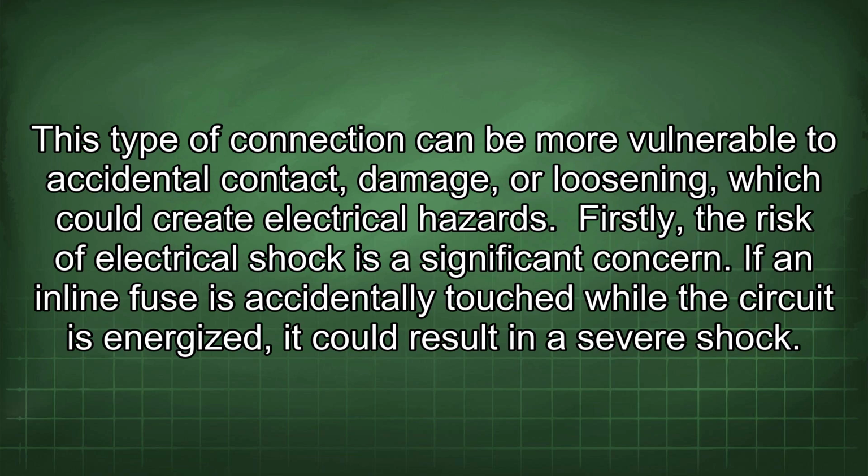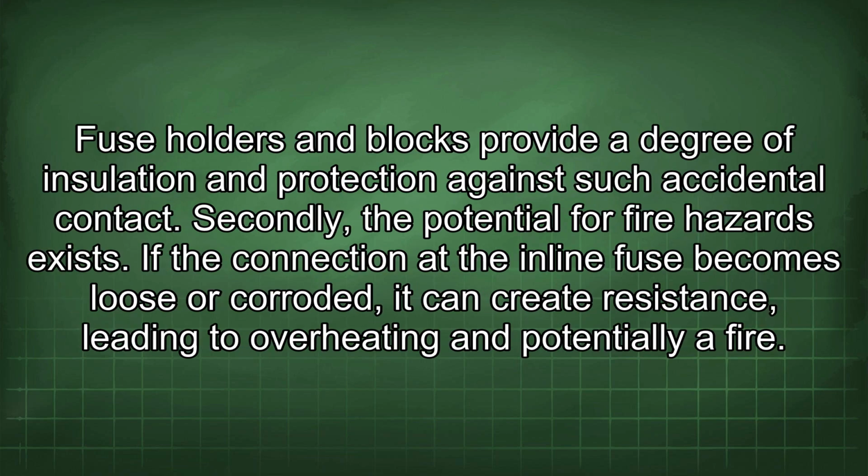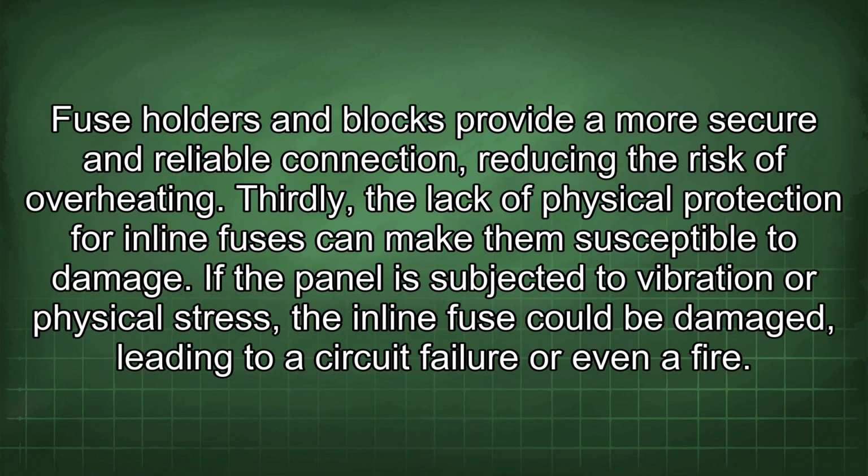Firstly, the risk of electrical shock is a significant concern. If an inline fuse is accidentally touched while the circuit is energized, it could result in a severe shock. Fuse holders and blocks provide a degree of insulation and protection against such accidental contact. Secondly, the potential for fire hazards exists. If the connection at the inline fuse becomes loose or corroded, it can create resistance, leading to overheating and potentially a fire. Fuse holders and blocks provide a more secure and reliable connection, reducing the risk of overheating.